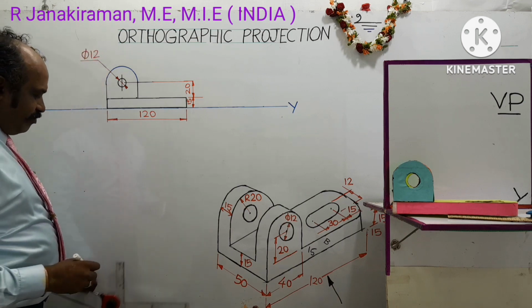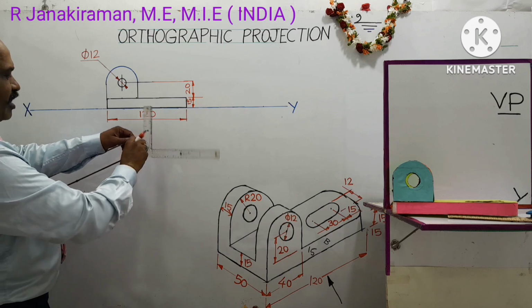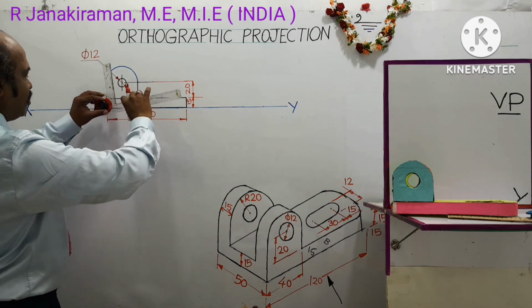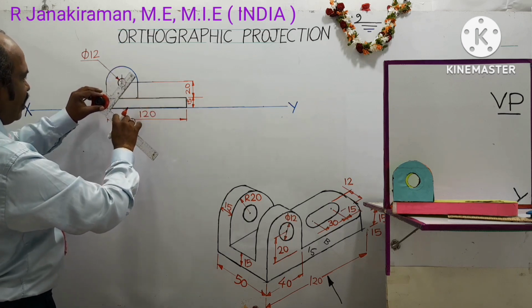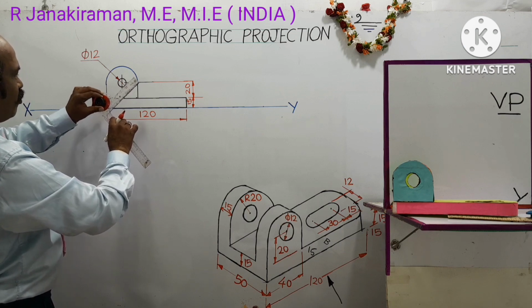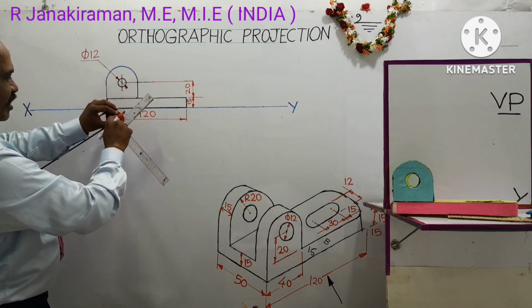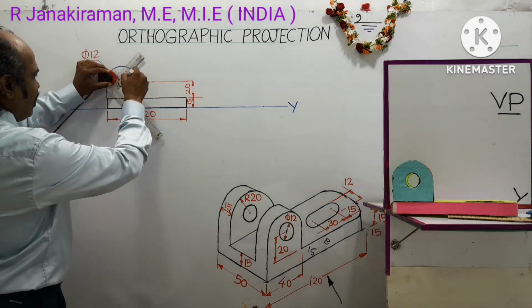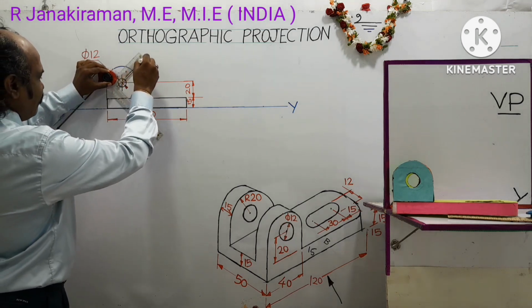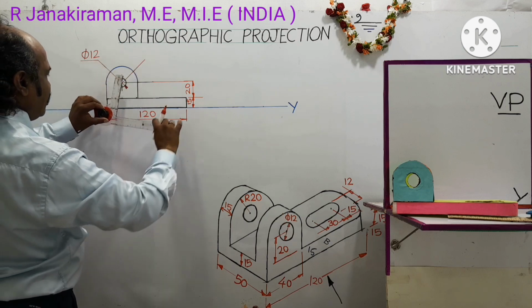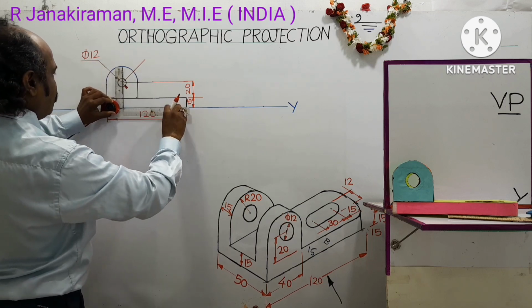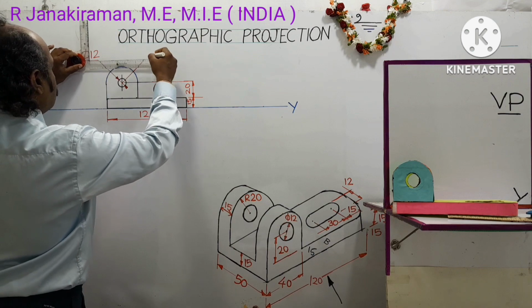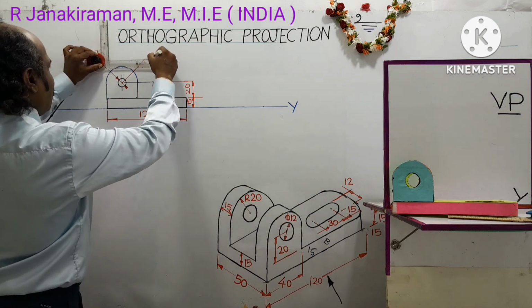Next, the same procedure is followed. Rotate the nut clockwise at 90 and the scale will be released. Set the angle to 45 degrees. Holding the scale, rotate the nut clockwise, so that you can set it to 45 degrees and draw one leader line like this to denote the radius of the circle. Okay, and reset your drafter scale. Draw one horizontal line like this.